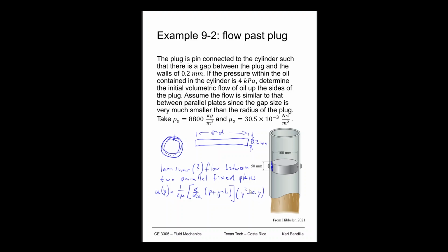All right, so what can we say there? Well, we can simplify this term here because our pressure change is going to be linear. Same with our height difference, and we can express that directly. So we can say that would be equal to 1 over 2 mu times delta P over L plus gamma times, now what's the height change?